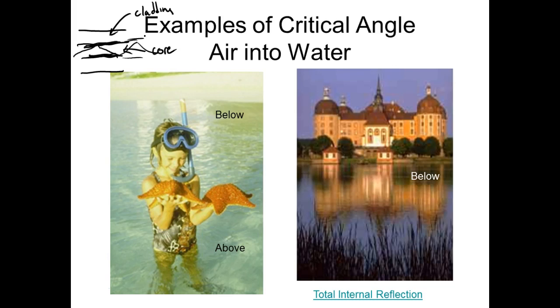So I can use a device called a capacitor. A capacitor blocks DC and passes AC. So that's all they did: they had a capacitor that their microphone went through, and it went onto the hot rail, and then they transmitted it through the rail. And on the other side, they had another capacitor that stripped off the DC and let them bring it in. It's a very simple system.